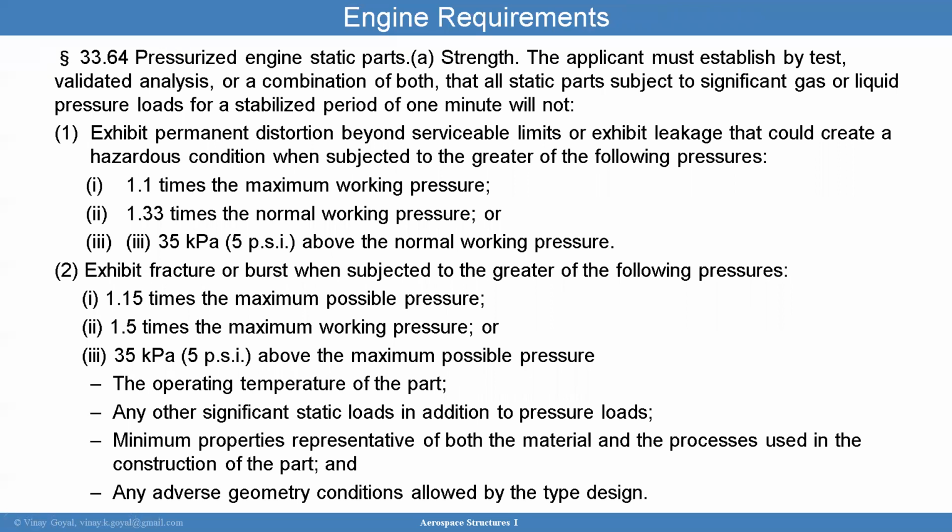You also have a number of specifications on the pressurized engine static parts. And that means that any component that's pressurized, that has gas or liquid pressure loads, has to be stabilized for at least 1 minute. You have to show good, and you have to make sure there's no permanent deformation beyond service limits or exhibit leakage that could create a hazardous condition.